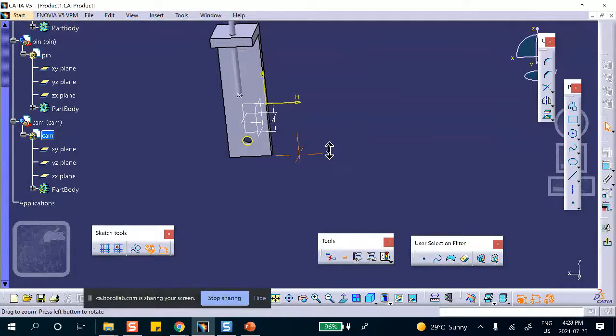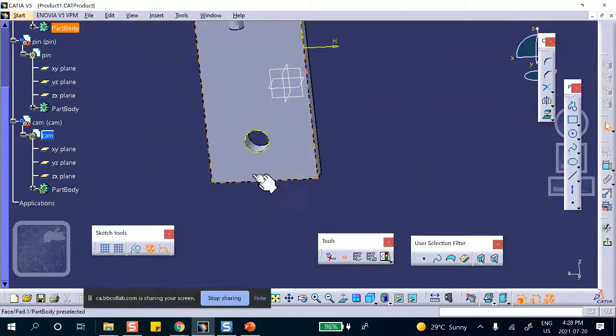By the way, if you want to change the radius of that, make it smaller, for example, you won't be able to do that because you have done a projection. Let's see if we can dimension it. We can dimension it, of course, and it's going to tell you what it is. But notice that it's put in parentheses. That means this depends on something else, and you cannot change it. Even if I try to make this 0.02, 0.03, it won't do it.